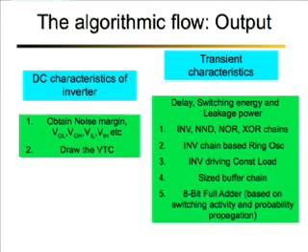So we are looking at both the delay and the power for a variety of different gates and cells. The typical gates and cells that we are using are inverters, NANDs, NORs and XOR chains. We also do an inverter based ring oscillator, which is a 5-stage ring oscillator, and we figure out the switching energy, delay and power dissipation in the ring oscillator. We also look at an inverter driving a constant load. This would more or less represent a scenario where an inverter is trying to drive a big parasitic capacitor like a bus, and then we figure out the switching energy and delay.